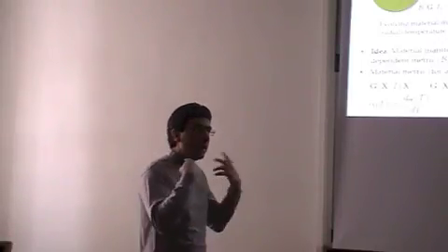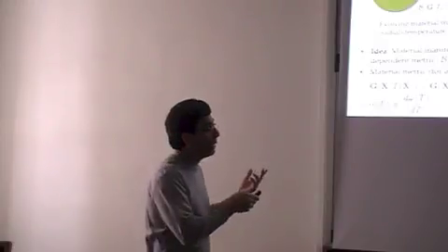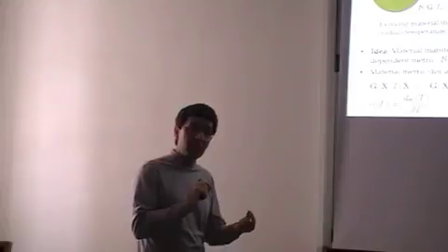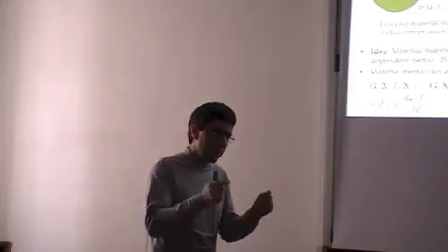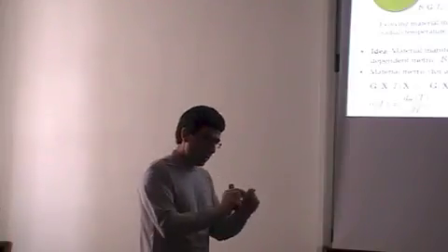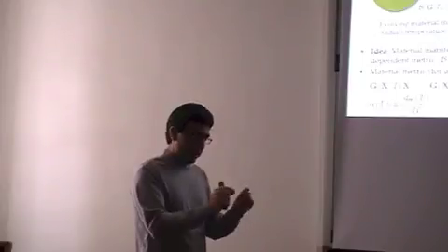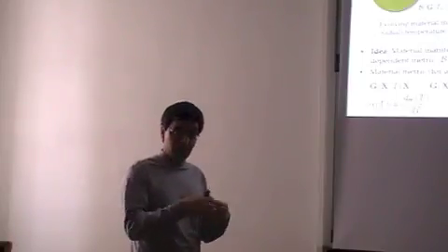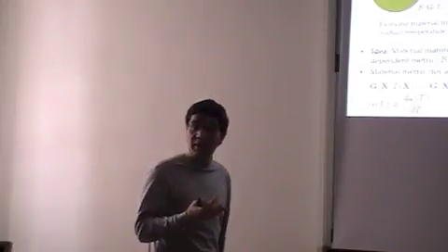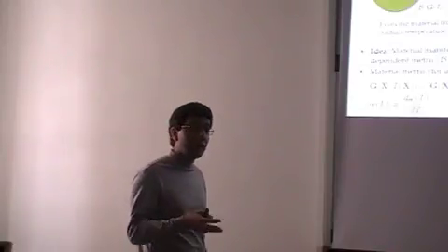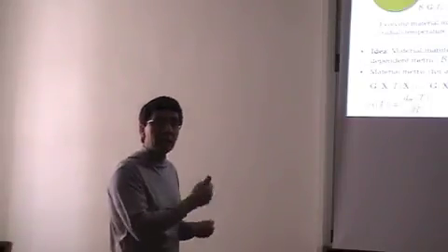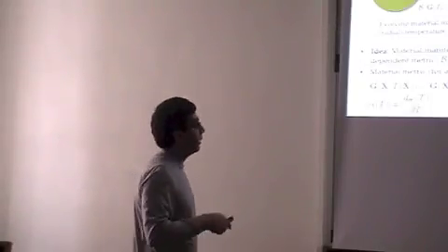But now let me imagine I put this body in a Riemannian manifold with a metric that explicitly depends on temperature the right way. Meaning that when I look at this underlying set here, the distance that I measure is really this, which is the natural distance that this temperature change is dictating. So in that Riemannian manifold, I'm stress-free by construction. So my problem is now a classical nonlinear elasticity problem.